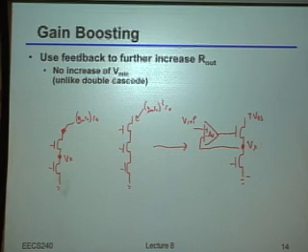Okay, so now if I have some small movement on Vx, what's going to happen on the gate of that transistor there? It's going to get amplified by the gain of the amplifier, right? That's kind of like saying that the gm of the transistor was increased by the gain of the amplifier, right? Because now, instead of, for example in this configuration, just having a bias voltage there, VGS would have changed by just Vx. Here, if I have some change in Vx, what's the change in VGS?